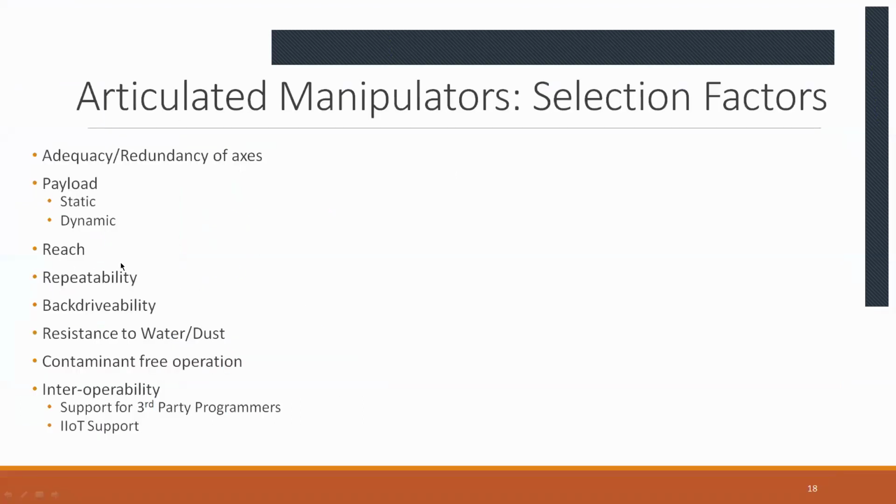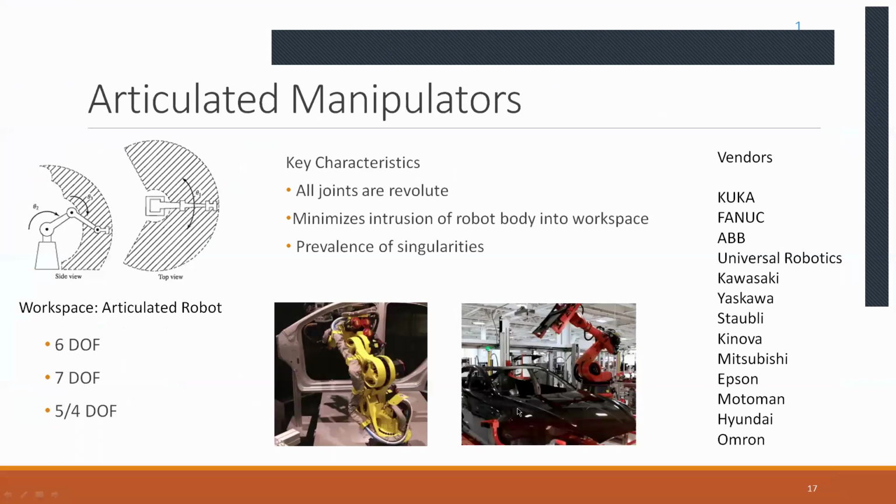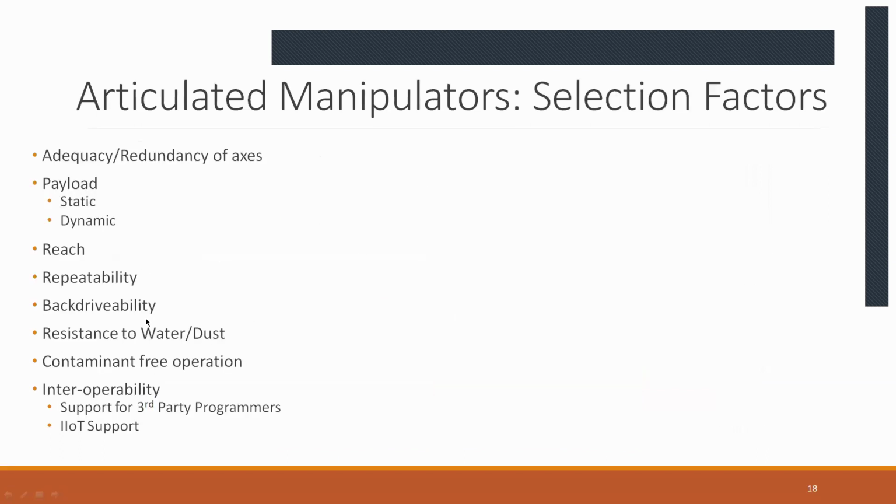Typically, the bigger the object that you're handling is, the higher the magnitude of repeatability it can tolerate. So if you are handling a car like this, then it would be okay with a repeatability of 1 millimeter or so. The same could be said for a spray painting or a welding application. But if you are picking and placing electronic components, then definitely the repeatability needs to be in the micrometer range.